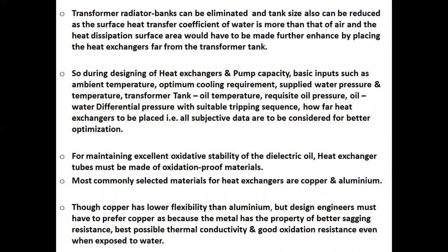Transformer radiator banks can be eliminated and tank size can also be reduced, as the surface heat transfer coefficient of water is more than that of air, and the heat dissipation surface area can be further enhanced by placing the heat exchangers far from the transformer tank.